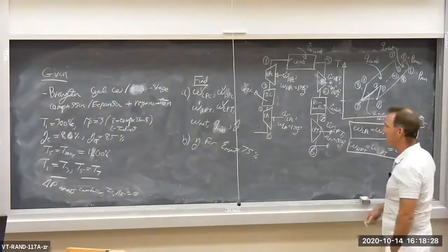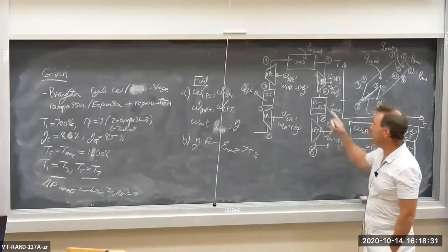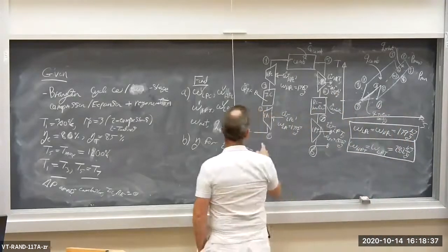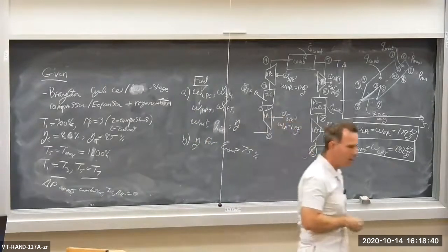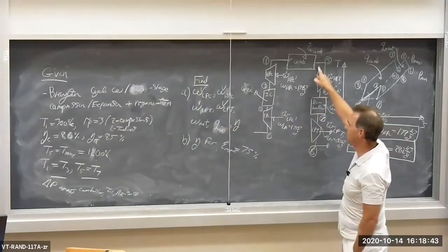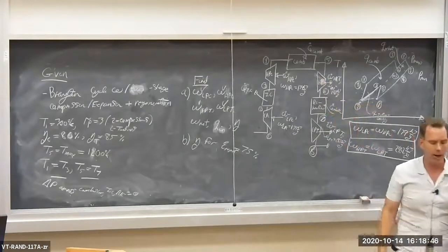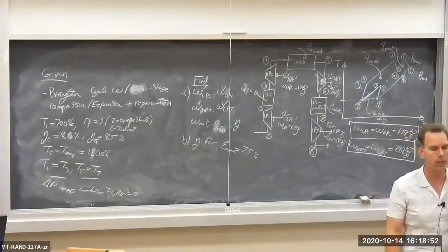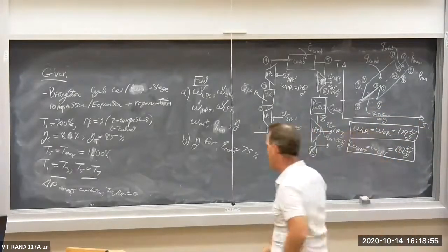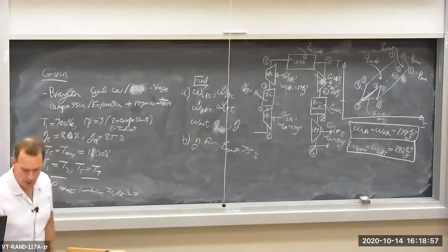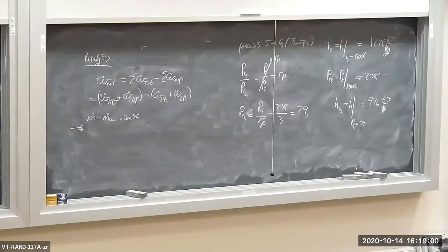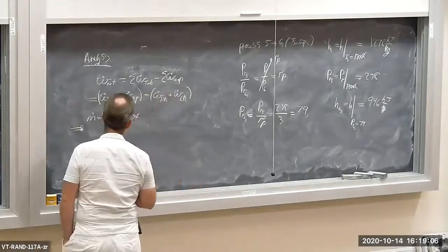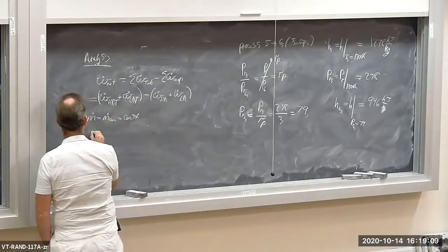So in reality, in a real Brayton cycle, you're actually going to have different mass flows through each part of the device. M dot air through the LPC and the HPC are going to be constant, but as soon as we get to the combustor outlet, M dot is going to be a little bit higher because you've added the fuel flow in the combustor, and then it's going to be higher still when you add the fuel flow in the reheater. We're not interested in that. We're assuming M dot is the same, and in almost all of these problems, M dot is the same for each device.